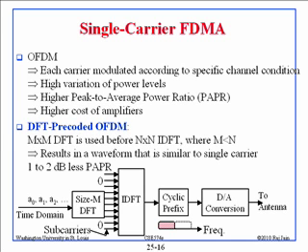So how do we do single carrier? Basically, we take the symbols that we want to transmit. These are in the time domain. We send them through what we call a discrete Fourier transform block, which is M by M. That comes out in the frequency domain as M frequencies, M subcarriers, right? This is the discrete Fourier transform. What does a Fourier transform do? It translates from time to frequency or frequency to time, right? So it comes out as M.